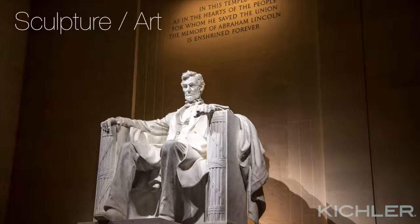How would you size fixtures to achieve this effect? The illuminance on the inscription might be 5 foot candles. It's got to be bright enough to read the text, right? The illuminance from each fixture directed at Lincoln might be 5 foot candles as well. There are multiple fixtures, which increases illuminance at the focal point where the beams cross, and the marble is more reflective than the limestone behind it. They also might be up to twice as bright, but lighting a sculpture with more than 10 foot candles can be a little too much.